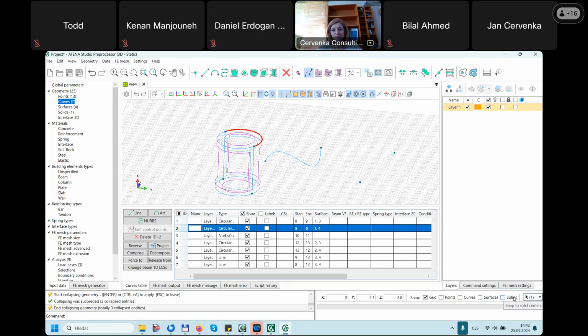And the rightmost button shows you the number of currently selected entities. You can use this to check whether there is really only 1 entity at that location. This is sometimes useful if you have complicated models where some entities may overlap each other, and it may be important to check that you know what is happening. Yeah, so please, Michaela, go on.